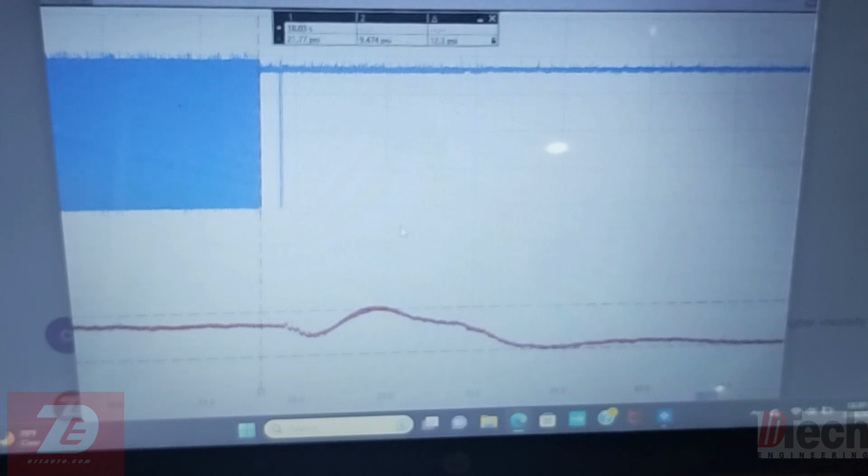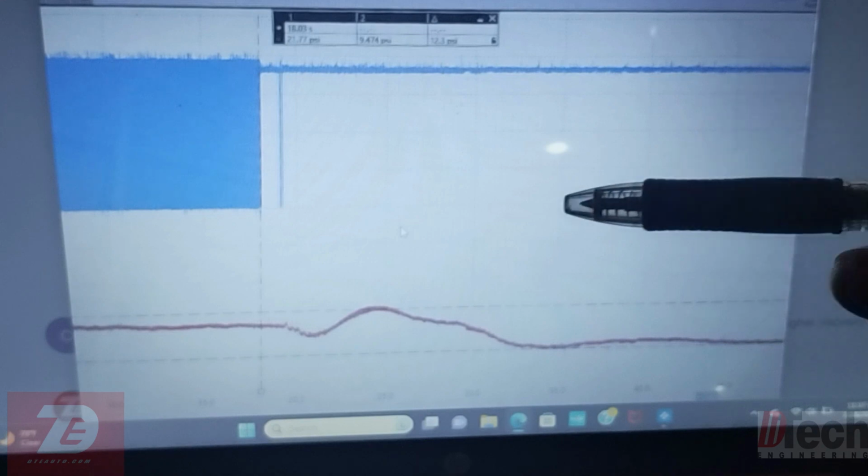But if you remember that a default for the valve is to go to full oil pressure feed in the default, and so even if the DME was bad, mechanically the oil control valve would supply more than enough oil pressure, other than the low oil pressure reading that we are actually capturing.